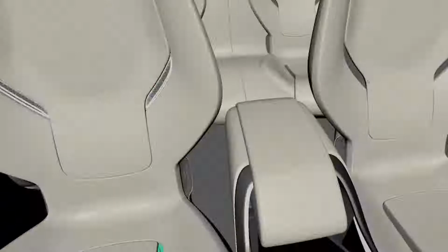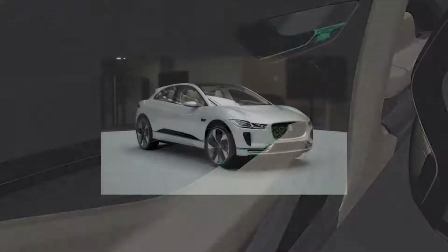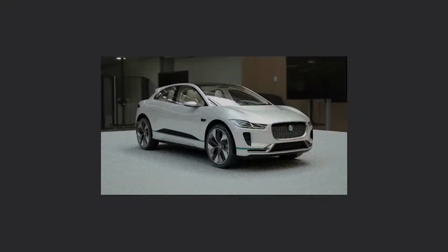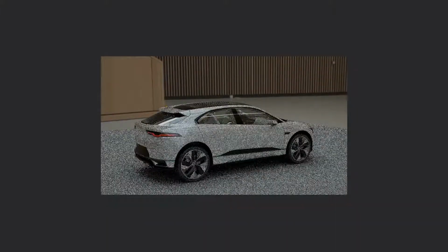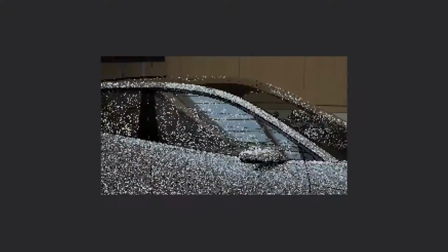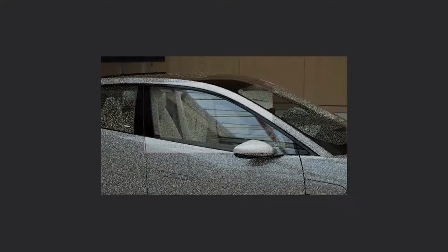So now we turn the IPR window back on and we have a good look over the car and the materials, checking that everything is as it should be, zooming into areas and checking that they have the correct breakups. We also will check the glass has the correct refraction properties so that you're seeing through it as expected in real life. So I also look into the paint shaders and make sure that the metallic flake is to the correct scale.